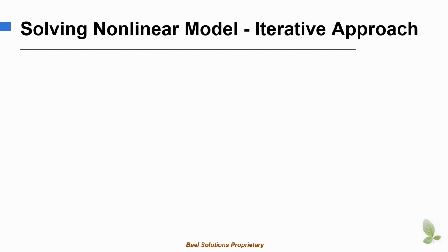In the previous slide, we saw how linear finite element models are built and solved by the finite element software. In this slide, we are going to see how nonlinear models are solved. Nonlinear models are solved iteratively using a Newton Raphson method.